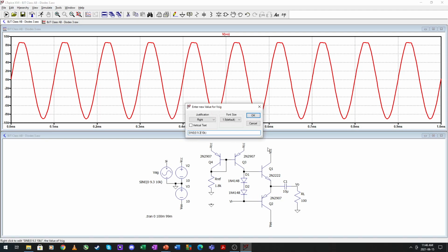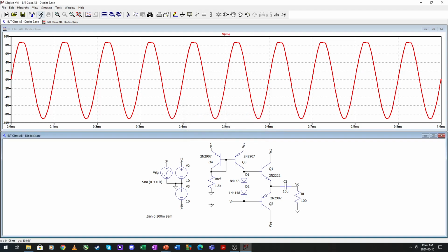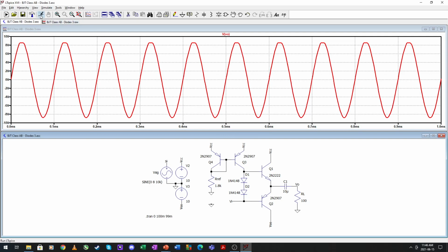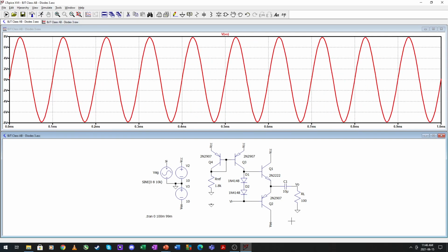So using an unbalanced current source like this is typically not a very good solution. You must rather have it balanced. So not even close. Rail to rail, not possible at all using this configuration. But using a current source like this is quite simple. I would rather go for the resistor bias personally. Onto our next